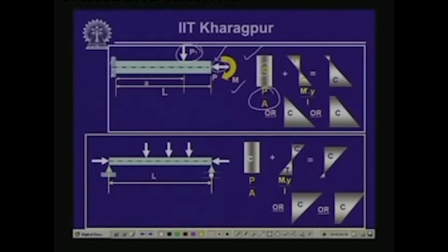Now, because of this bending moment M, at any section if we compute, on this side of the load it will be just the M, but if we take a section over here and draw the free body, then there will be moment due to this lateral or transverse load and the external moment M. So, at any section we can find the bending moment because of this transverse load P and moment M, and if we call that moment M dash, which is the combination of M and the effect of P, then the corresponding bending stress in this member will be M dash Y by I, as we have seen earlier. Now, this is going to cause tensile and compressive stress.